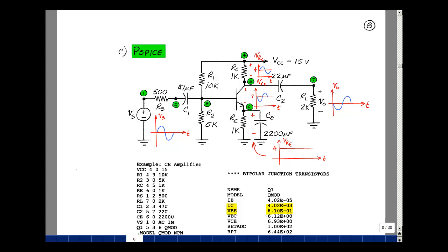But I want to show something here. If you take a look at the voltage across this resistor, the collector emitter, and the emitter back to ground, the voltage at any instant in time has to add up to 15. Here it's on the average 4 volts, 7 volts, and 4 volts. I get 15 volts. If this starts to go up, this starts to go down so that the total stays the same. The sum of these two is always equal to 11 volts.